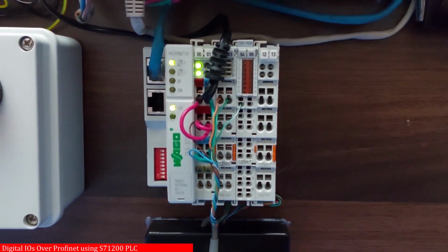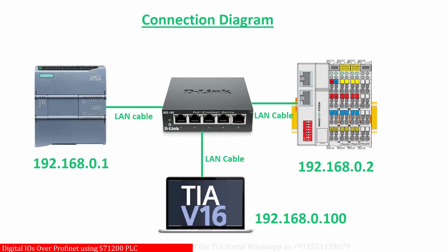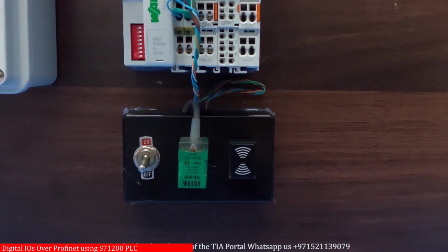As you can see, we have connected the S7-1200 PLC with the field bus coupler 750-370 with an Ethernet cable. We have inserted one input card with 8 digital inputs and one digital output card with 16 outputs on the Wago field bus coupler. The diagram for the connection is like this. Next we have connected a switch and one proximity sensor at the first two input terminals of the input module and the 24-volt buzzer at the first output terminal of the output card.